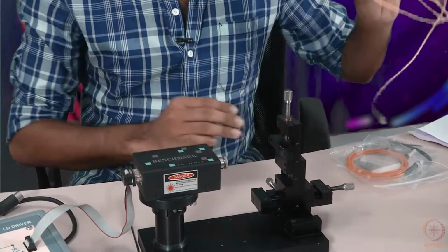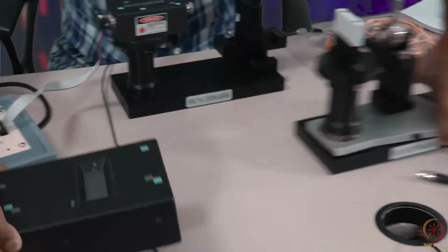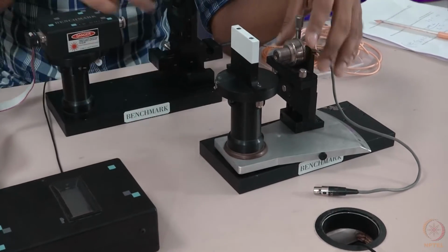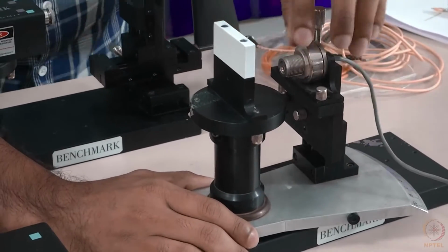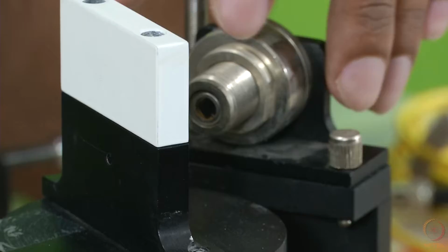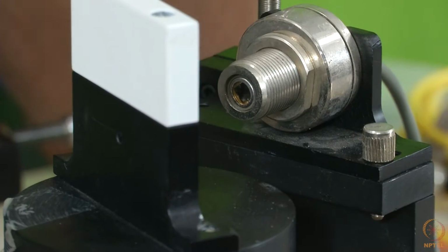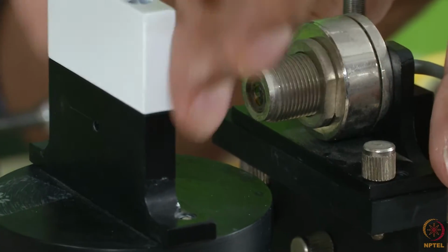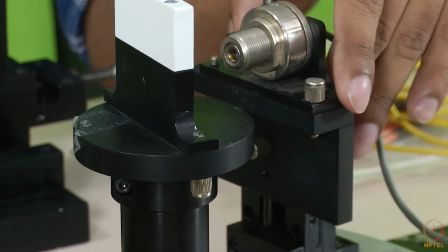We'll move into the detectors. So here we have the detectors. I'll just take this aside. So actually the fiber tip will come here, and it will launch the laser into this rotation stage. And in this metallic part, you can see the photodetector here. So it is actually a slightly big photodetector, and you're going to use it in a free space kind of application. So you'll be launching light from this part. Light will fall on this, and you can actually rotate this around.